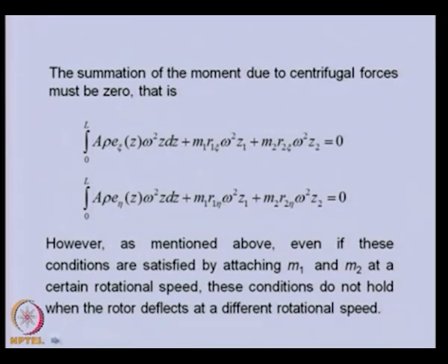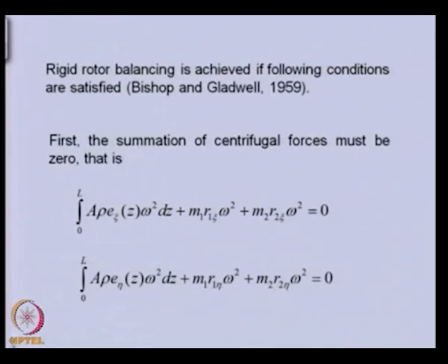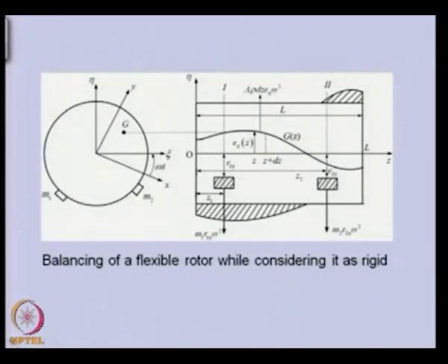Now, to balance such a rotor in which there is continuous variation of the eccentricity, one way we can do it theoretically is to put some kind of continuous mass here. You can see the shape of this should be the same, maybe the height may be different proportionately, according to the radial position of the correction mass.